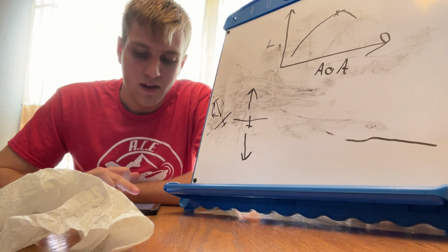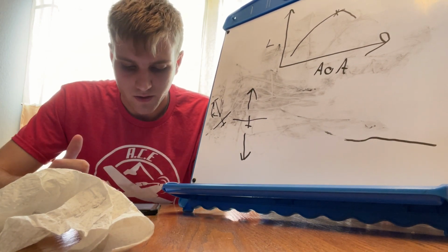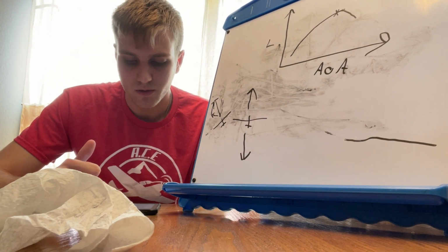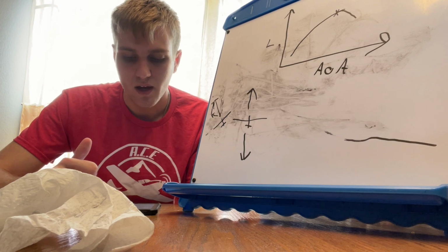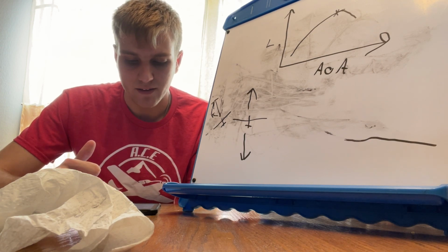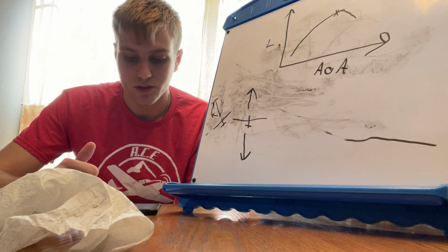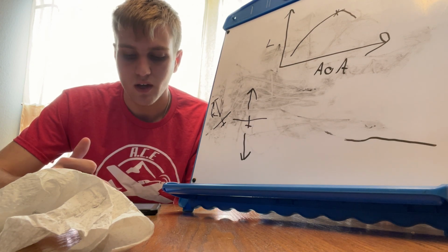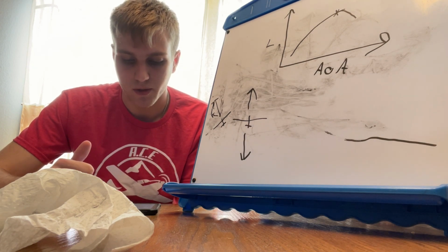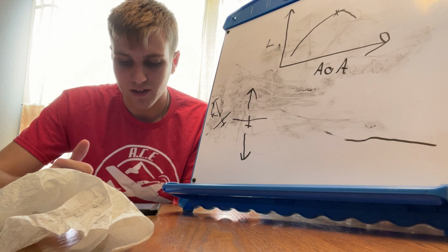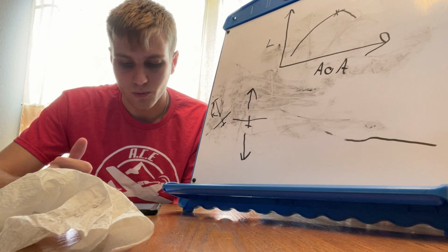Okay, here we go. In aerodynamics, the maximum load factor at any given bank angle is the proportion between lift and weight and has a trigonometric relationship. The load factor is measured in G's, a unit of force equal to the force exerted by gravity on a body at rest, and indicates the force to which the body is subjected when it is accelerated.